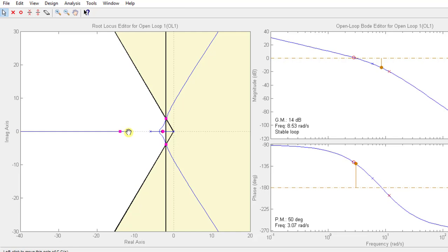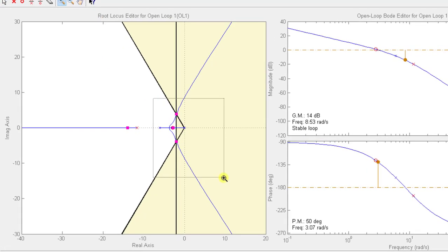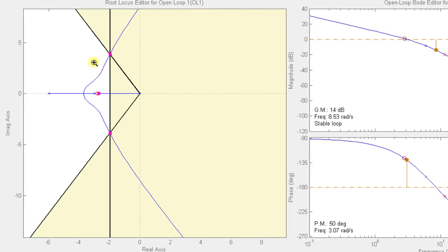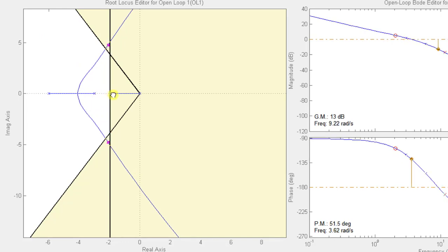And also you can have a number of different combinations of lead compensators that you can design to have this requirement fulfilled. Even in this problem, you can see that I have changed the pole and the zero abruptly and just tried that the root locus passes through this intersection point, and there can be a number of different alterations. I mean, we can have different sets of locations of this zero.